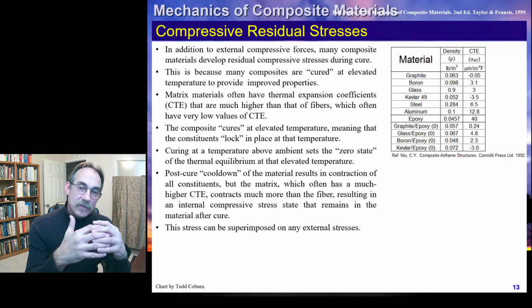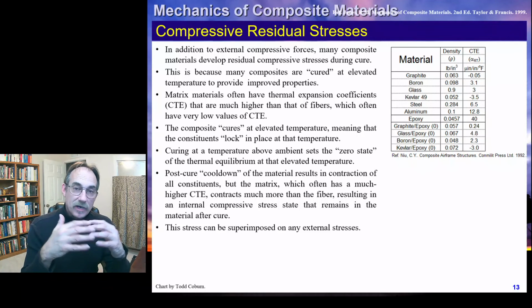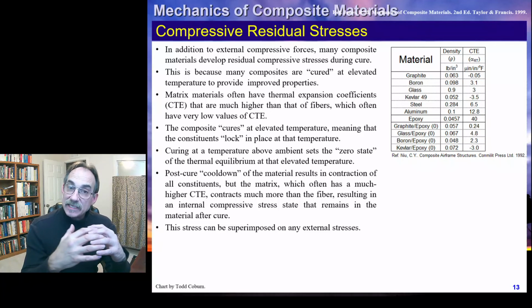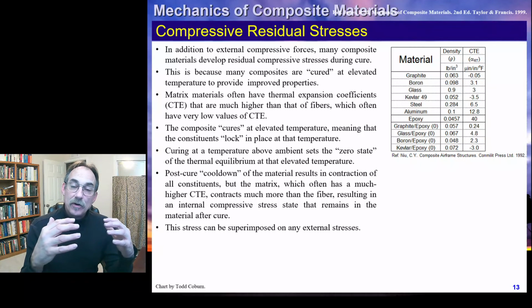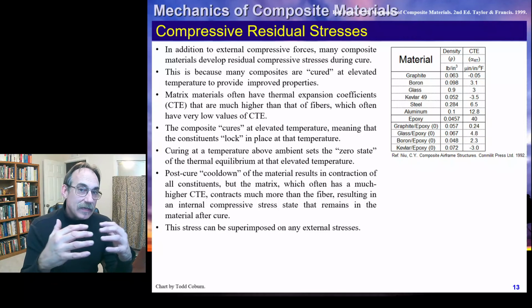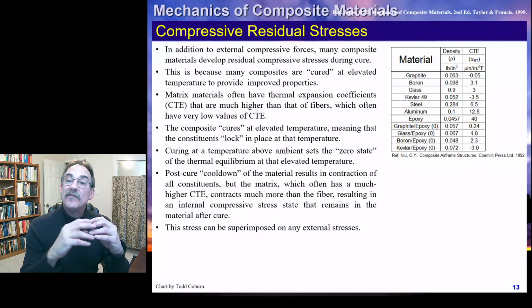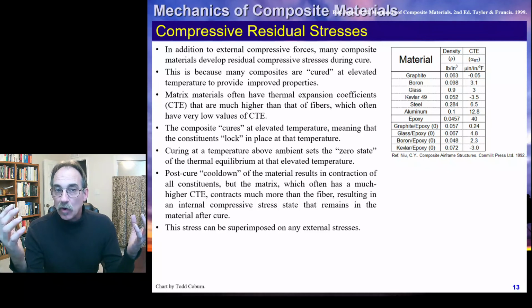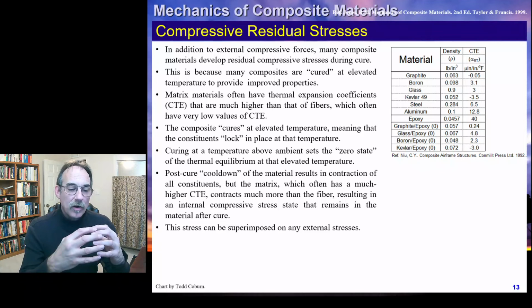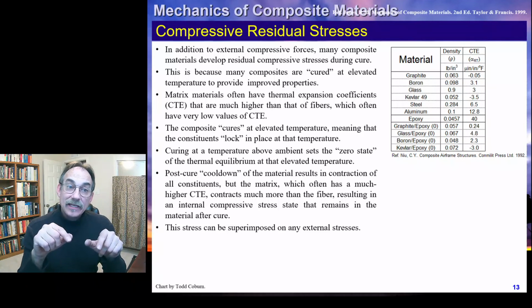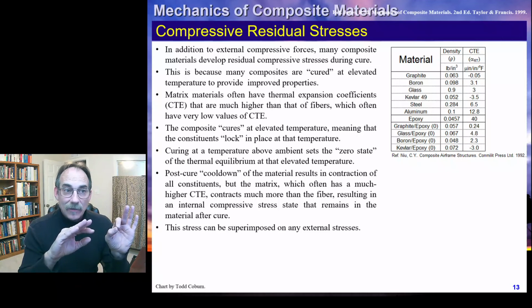If you're curing something and you get all those residual stresses, whatever they are, and then you test to failure and measure the strength at that test level, and that already has the same level of baked-in residual stresses, then you can just focus on the applied loads without having to get into this detail.